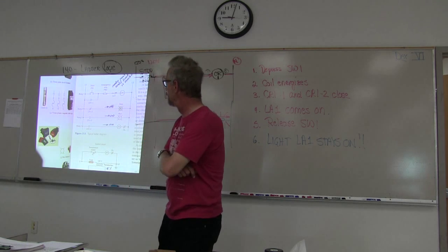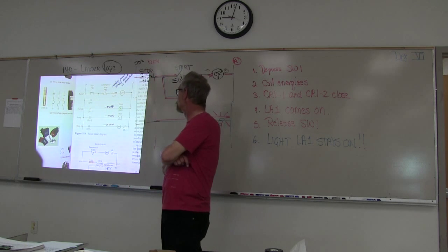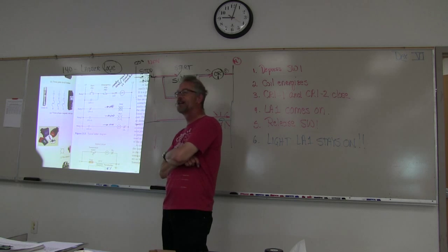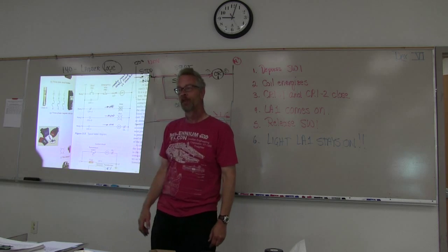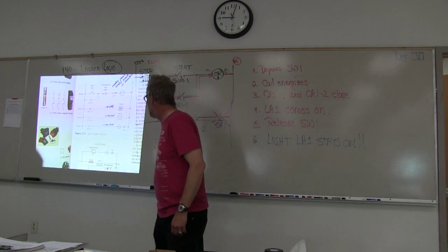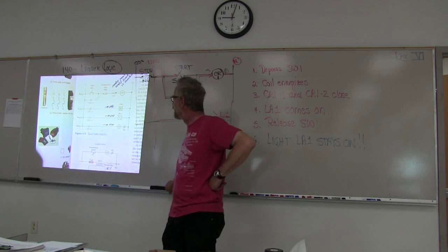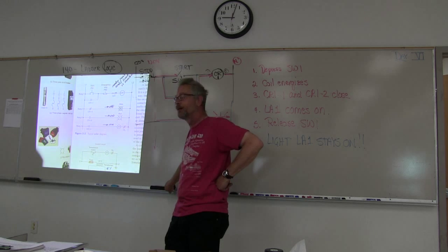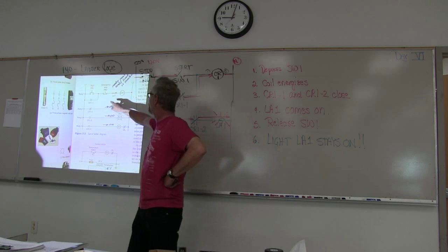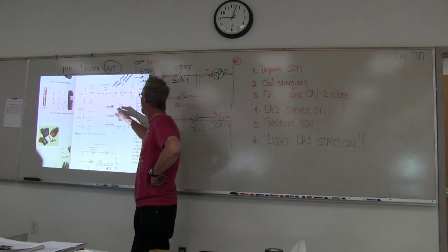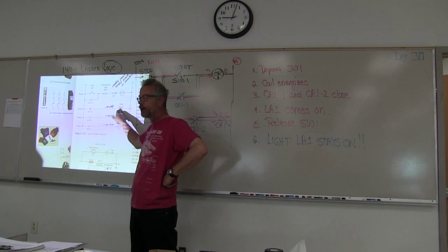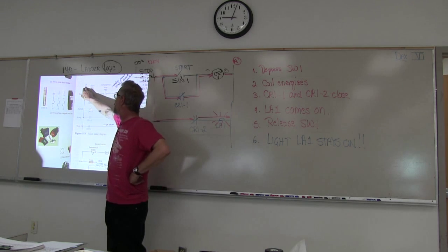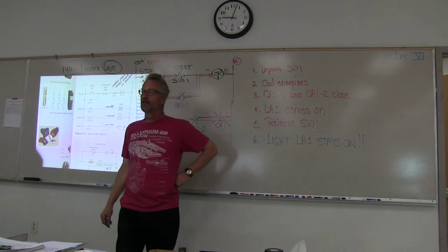That's the only reason you would really bust the emergency stop, if somebody gets their hand caught in the motor, and in that case you don't really care whether the light's lit or not. So it kind of does its job, but it's not as complete as it could be. That's something the engineer has to decide. Do I want to put my emergency stop here so that I will have a red light to indicate that there's still power to that machine and there's still a hazard? Or do I want to put my e-stop up here so that everything is shut down?